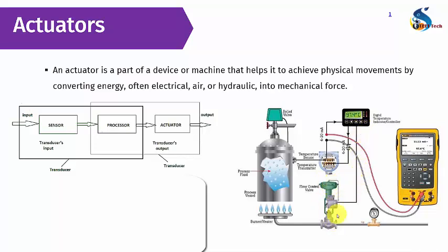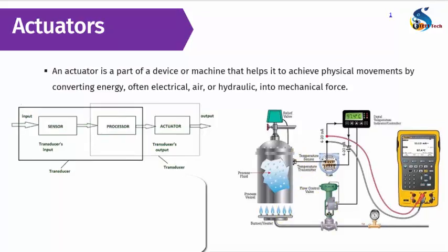The actuator is our industrial muscle. It receives instructions from the control system. In our example, the actuator controls a flow control valve connected to the furnace. If the liquid temperature is too high, the control system signals the actuator to adjust the valve, regulating the heat output from the furnace. So just as our brain tells us to move our hand away from fire, the actuator responds to the sensor's input by adjusting the flow control valve. Together, sensors and actuators create a dynamic feedback loop, ensuring effective and precise control in various applications.